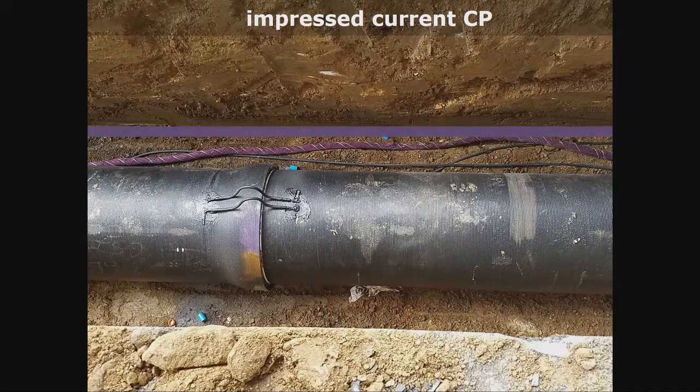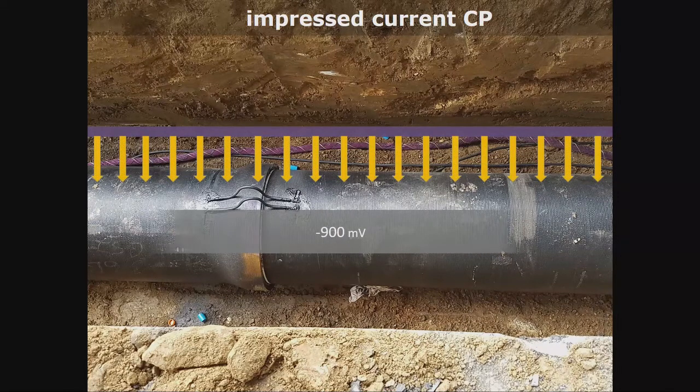Well, we're basically putting a waterfall of energy on that pipe, and we're changing the current. So we're making the pipe the winner on the field, and the anode the loser, and the anode will be eaten by the corrosion instead of the pipe. What does that mean for the life of the pipe? Well, that means that the anode will have to be replaced probably about 3 times in the span of 100 years. So it has to be maintained. If you don't maintain it, then the pipe gets to be the loser on the field.